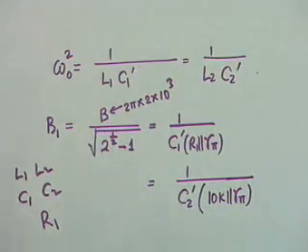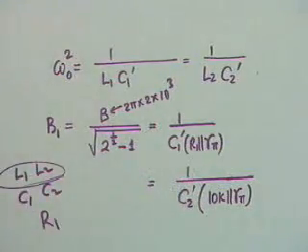You would normally like L1 and L2 to be equal, because this is the problem point. Winding an inductance of a specified value is a problem. So if you have wound it once, then you know exactly how many turns you have to use. So normally you would choose L1 equal to L2. That constrains you to 4 equations, because you have made one choice, and the rest can be calculated. More on Monday.